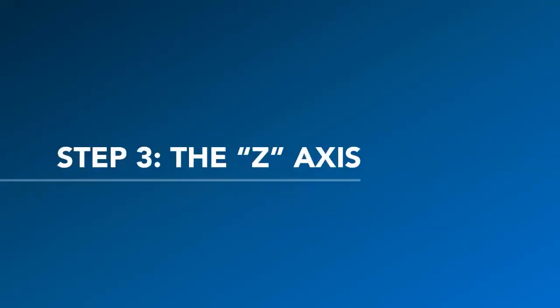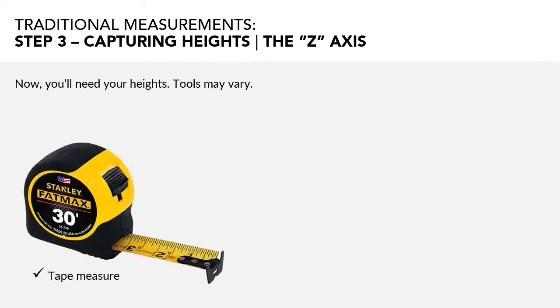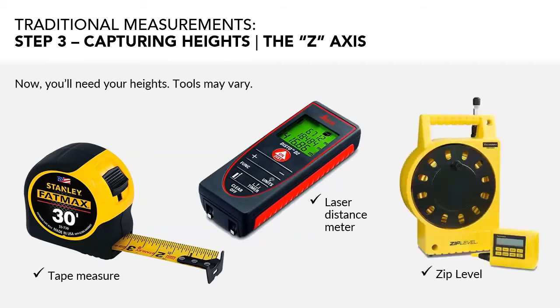Now let's talk about collecting the Z-axis measurements or height information using traditional methods. You can use a tape measure, as we all know, to measure all the risers and stairs, for instance, maybe drop it down a balcony, run it up a wall, things like that. A laser distance meter or disto can perform trigonometric functions instantly and get you heights in all sorts of ways. The first two of these tools you might already be using to measure all other aspects of your plans, but the third is used exclusively to gather height information, and that is the zip level.